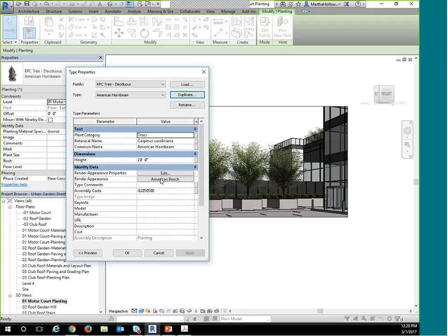The other big thing is you could just go, well, I'm just going to put all oaks, and they all are going to be the same thing, and I really don't care about the additional information. But you would be limiting yourself to more standard CAD uses as opposed to a true information modeling. And so I do recommend that you would create a new type as you go along for each of these.